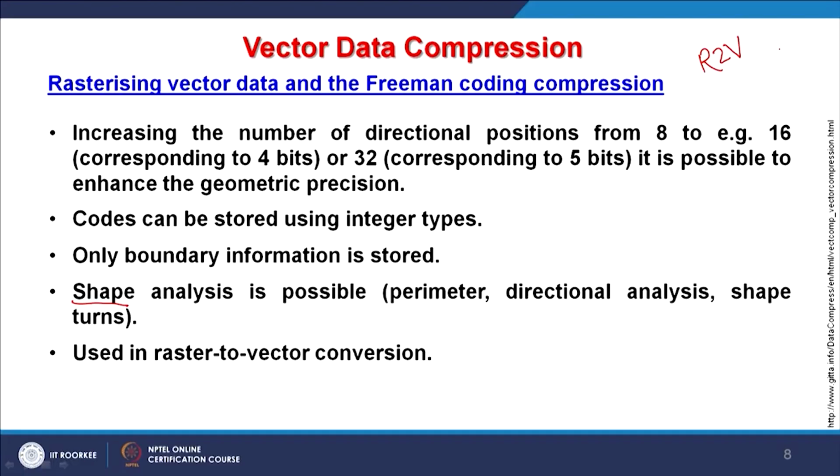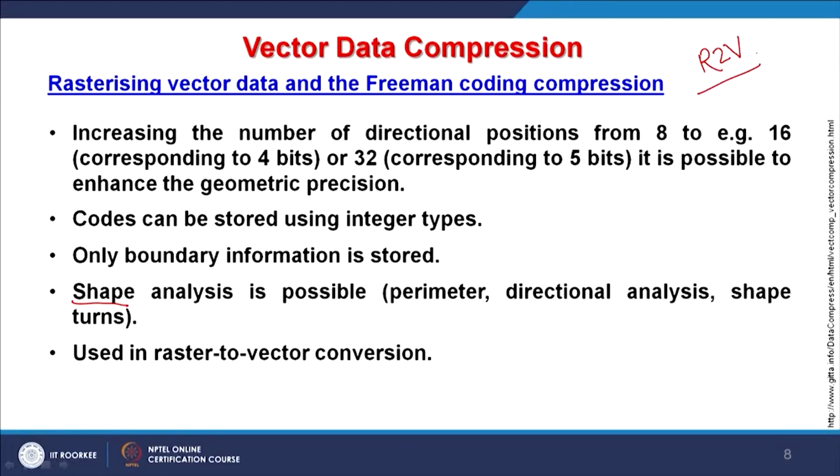Suppose I am having a Survey of India topographic map in which I am having multiple layers in different colors, and I want to extract only contours. When I scan that using a large format scanner, basically I am generating an image of that topo sheet. That is nothing but the raster. And if I submit that scanned image of a topo sheet to this software, R2V, then what is going to happen? It will convert, but it will give us very erroneous results.